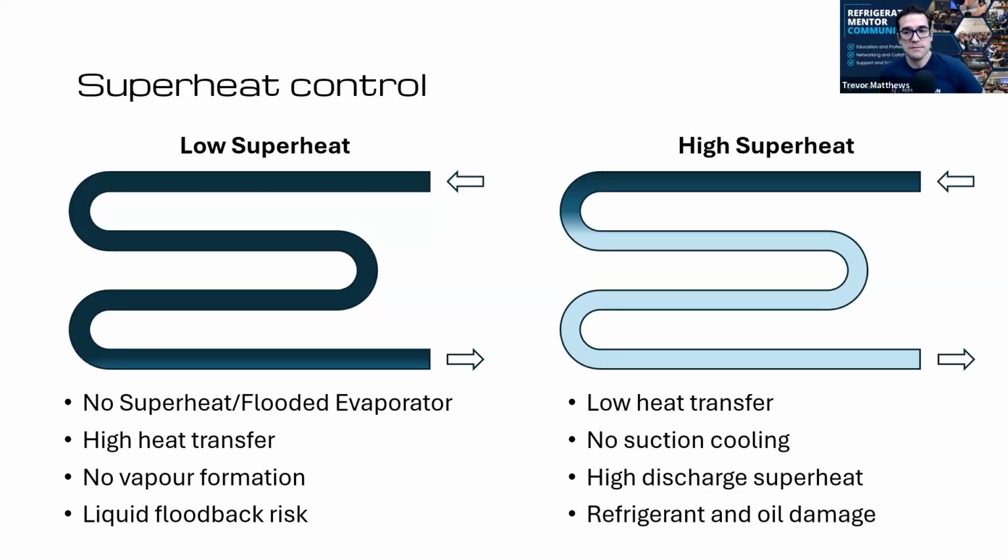I don't know if you've encountered that in the past, John. So yeah, if your coil's flooded, say your EEV is stuck open, then obviously your coil temperature is going to drop, and you'll end up with ice formation, lack of airflow, lack of heat transfer, and it eventually compounds the issue to the point where you start seeing flood back to your compressors, oil washout, all that kind of stuff. So yeah, there's a huge compound effect in both of them, low superheat or high superheat. And this is just in refrigeration in general. Awesome. Thanks, Chris. Good stuff.